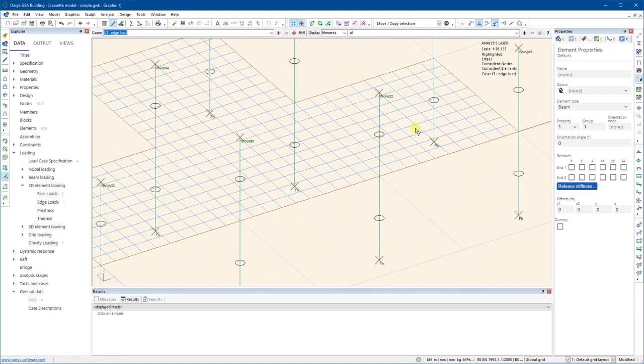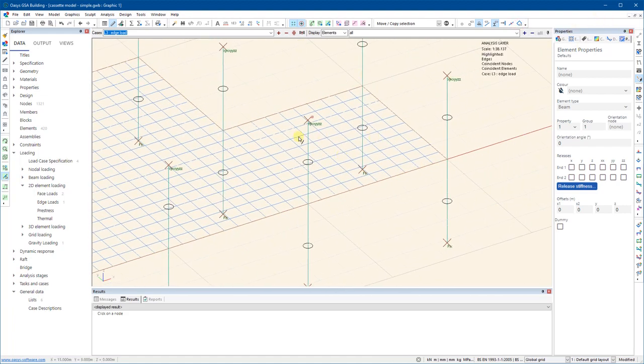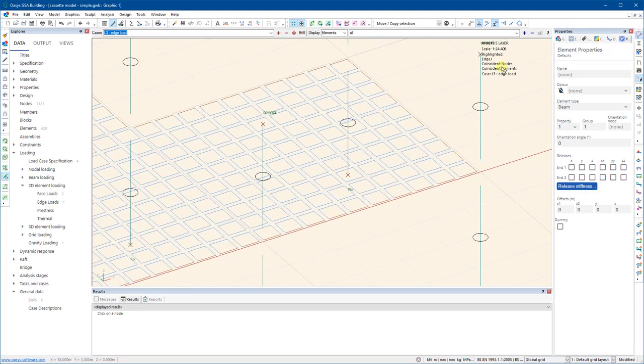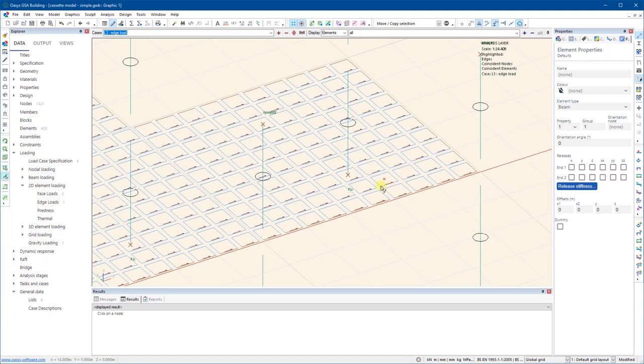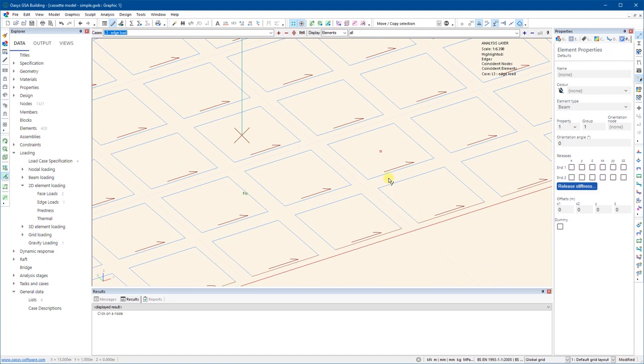So if I zoom into my model, you can see I've got a set of 2D elements to form the floor plate. We've got the shrink button there, but you see the elements themselves, there's nothing on them. If I were to click this button, which is the label of the 2D element edges, you see the arrow on the edges of the elements itself.